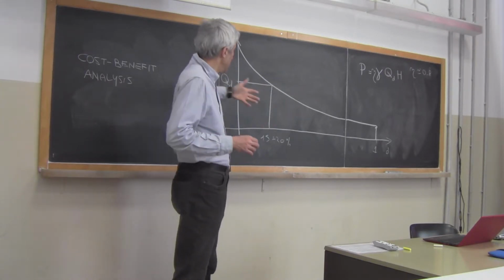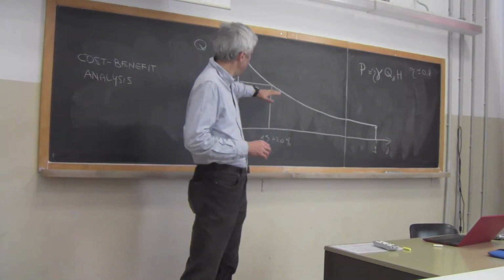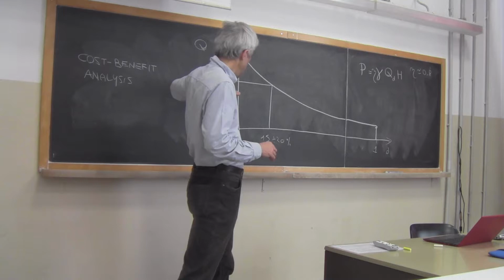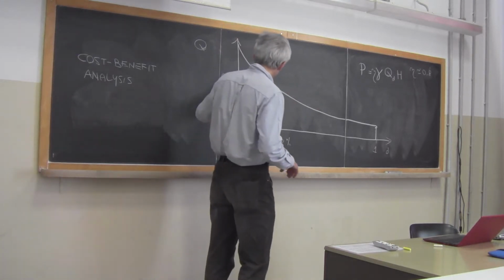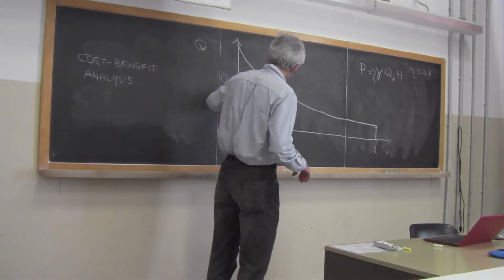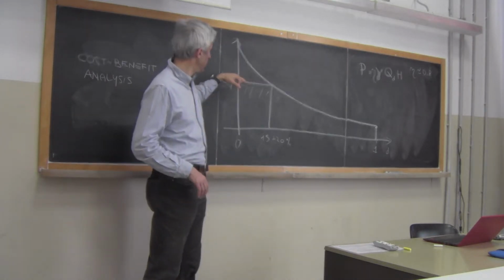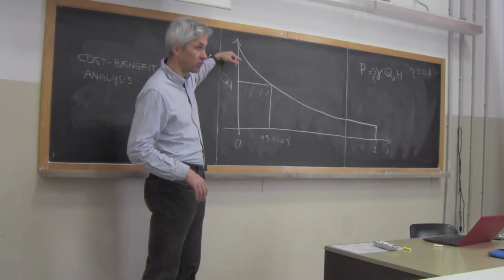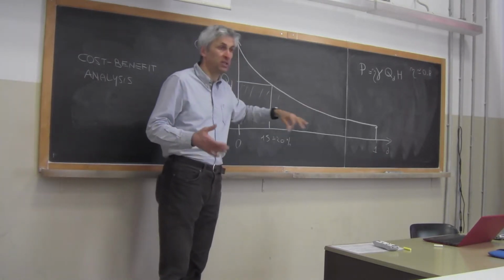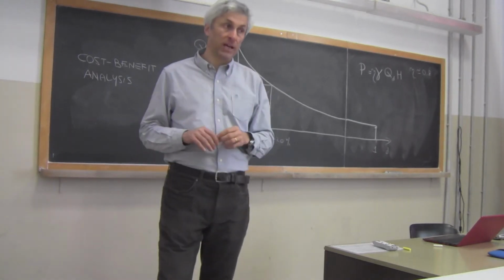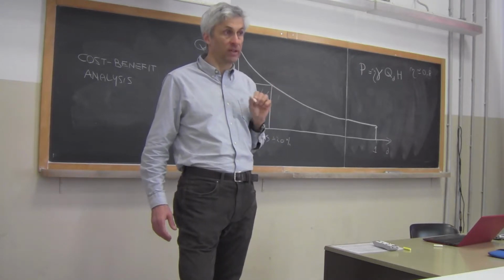So one may say, well, this is easy to reply. I take the area that is below the curve up to here, okay? And I don't want to highlight it, but anyway, it's the area, it's this one. And I have to stop here because for flows higher than the design flow, I cannot get it. And therefore the area below here could be our answer. But actually it's not like so, because there is the environmental flow to release. We already defined what is the environmental flow.